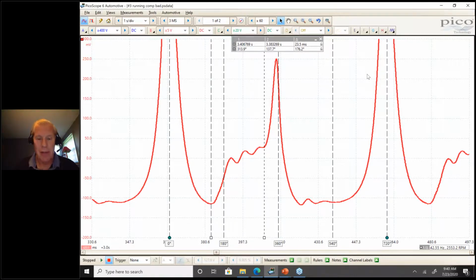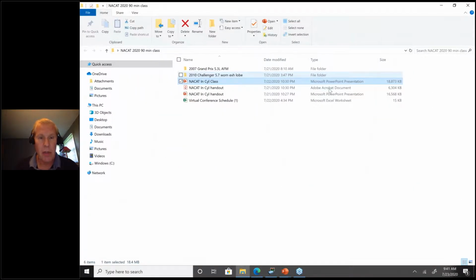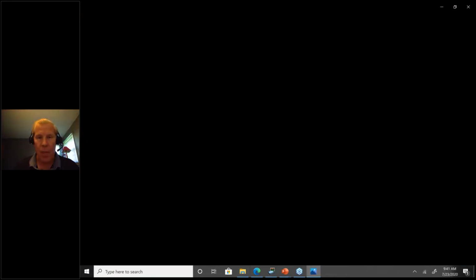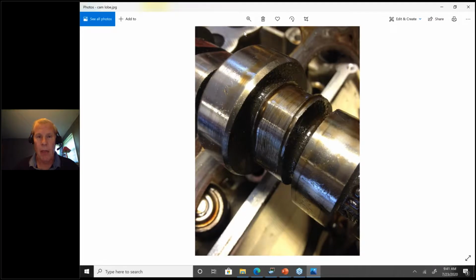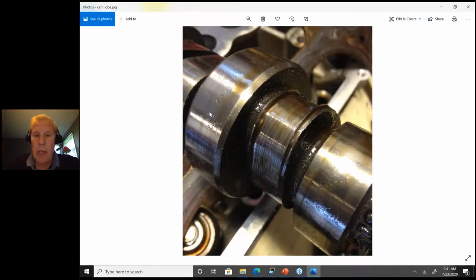You know what's wrong. I know you know what's wrong. Let me show you what's wrong. Once again, I'll give everybody a moment. Take a look. We can see it, John. Thank you, Kurt. So you can see that the lobe is worn out. And of course, the roller lifter is shot as well, but the cam lobe is completely worn.